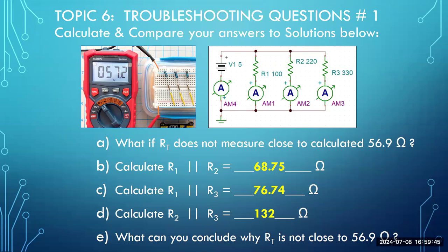On the preferred calculator, it'll show you some number with an engineering prefix, the lowercase m for milli, in the upper right-hand corner. All right, one more calculation to do, and that is 132 ohms, which would result as your total resistance if only R2 was left in parallel with R3. This presumes something was wrong with the first branch. So you end up with two resistors in parallel totaling 132 ohms.